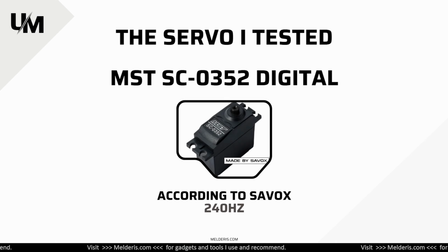Okay, so what was happening, this servo was accepting only maximum 240 Hz, but I was trying to push in a 333 Hz refresh rate, which is almost 100 Hz more than this can handle. And that is why I had issues, that it was buzzing, it was not working properly, and it was very quickly heating up.